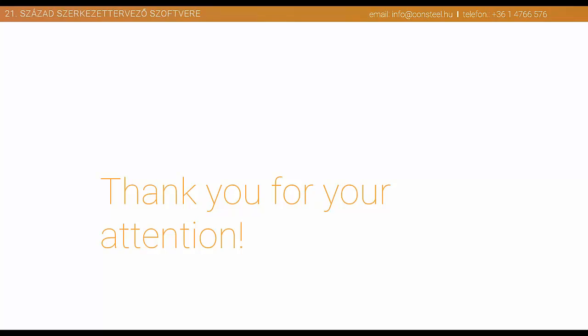So now, even if for any reason a new version of ConSteel would propose another value, it's still in the hand of the user to override this proposal and select the eigenvalue, the buckling shape which he or she might feel appropriate. So don't be surprised if sometimes these automatic proposals would give different results between versions of ConSteel. The user with his engineering knowledge can always override these proposals and find the appropriate results.